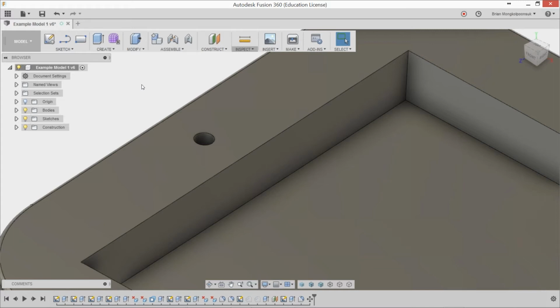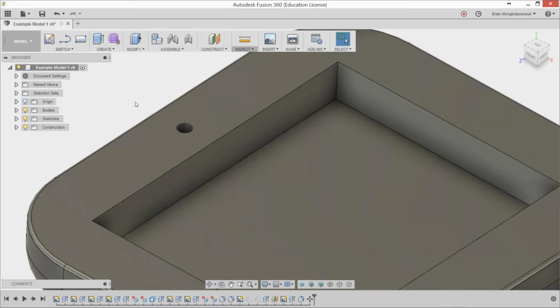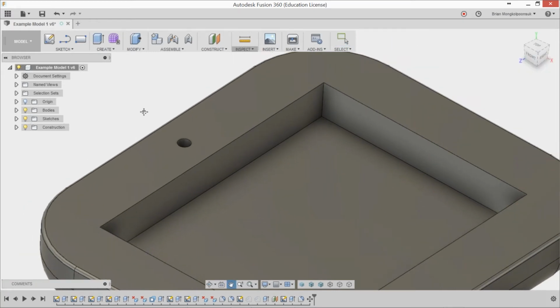So anything like a fillet or maybe a chamfer on an edge, and you want to see that modeled in there, just do direct edit modeling inside of Fusion 360 and make those changes. You don't have to go back to the customer, ask for a change, and waste time there. Just do it yourself. Exactly. It's super powerful, and it definitely works on those external or foreign files that come in.